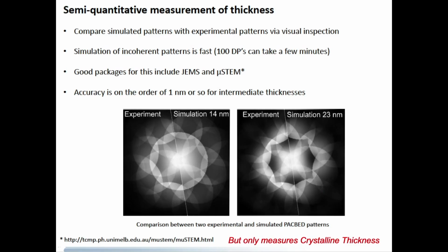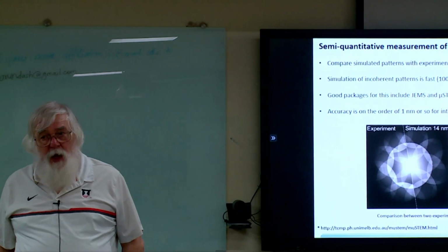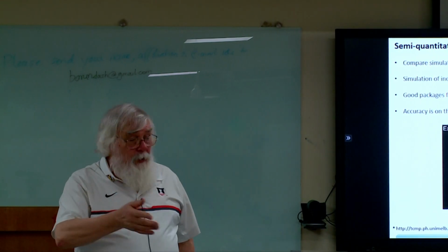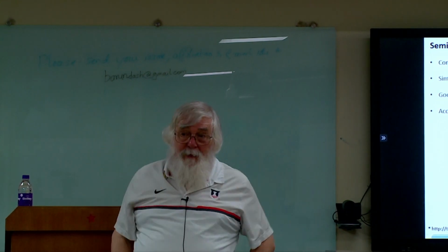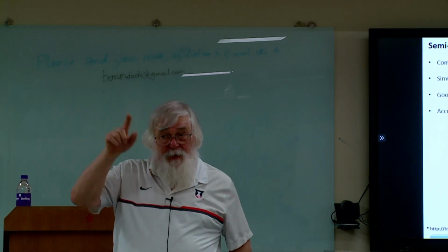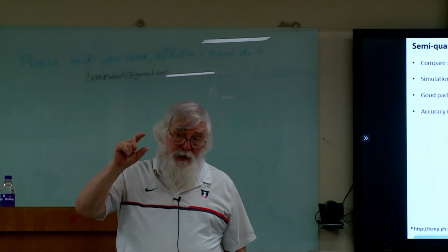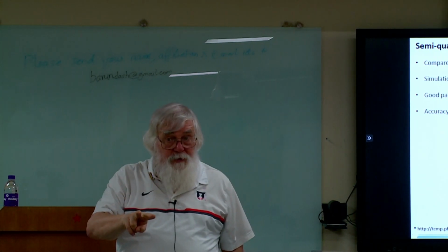Now, what's good about measuring sample thickness with convergent beam patterns? It only works for crystalline materials. So if you have an amorphous sample, can you measure the thickness with convergent beam diffraction? No. Okay. There are other tricks you can use. We'll talk about them later. But what happens if you have a crystalline area with an amorphous layer on top and bottom? You still measure the thickness of the crystalline area, but remember you've got amorphous material on top and bottom. So what's the question you're asking? Is the question how thick is the crystalline area or how thick is the total sample? Those are two different questions.